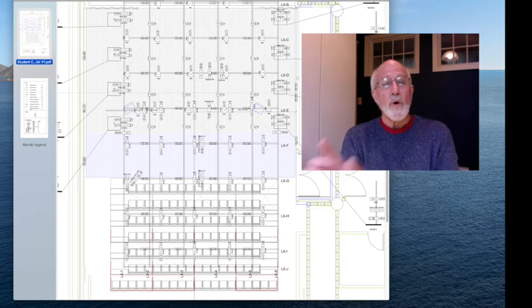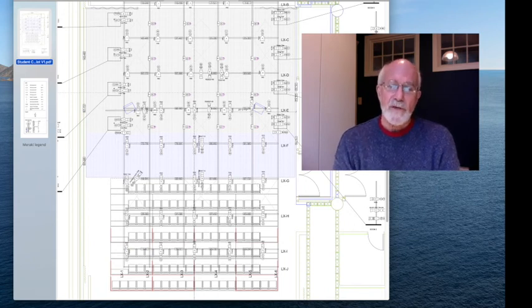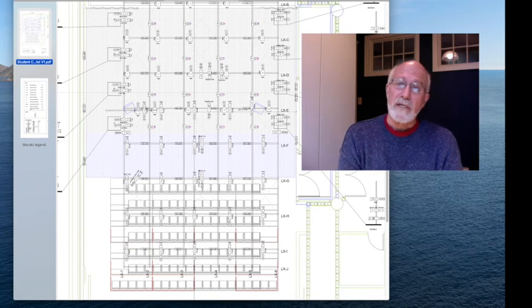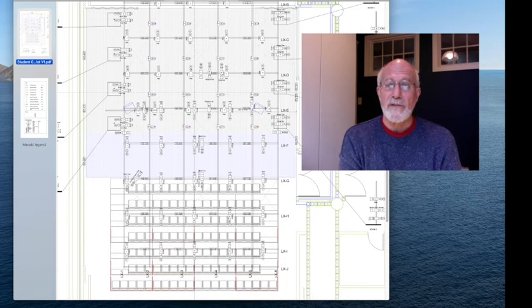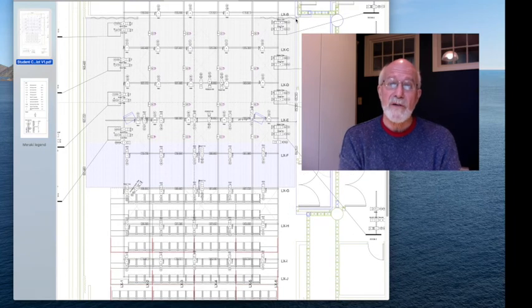And more importantly, you're extremely unlikely to be using circuit 1 way out here and circuit 1 way out here at the same time, because it can't be lost that if you plug into circuit 1 in 2 locations, the instruments connected that way are going to do exactly the same thing. They're going to turn on, they're going to go to the same percentage of their maximum intensity, they're going to turn off, they're going to act as if they were hardwired together, which in effect they are.